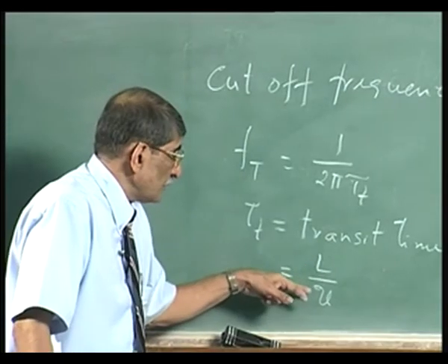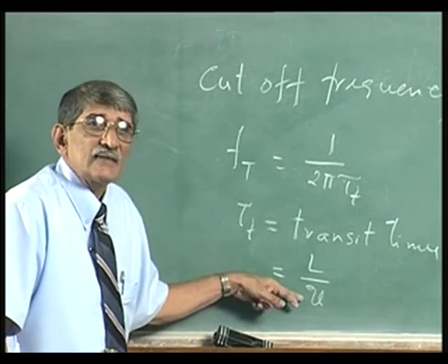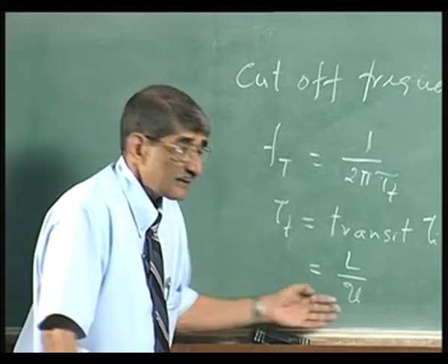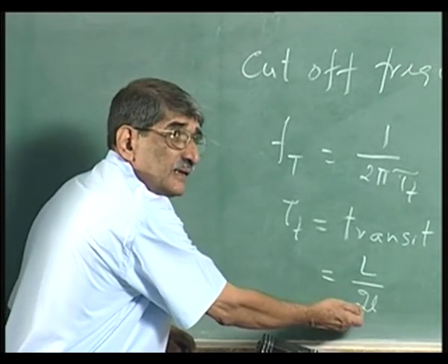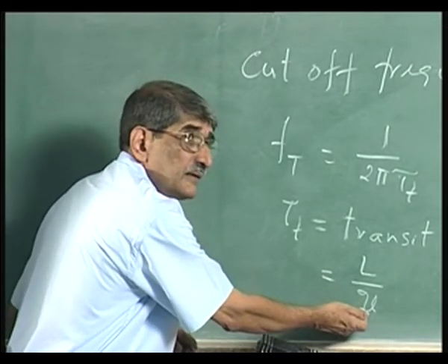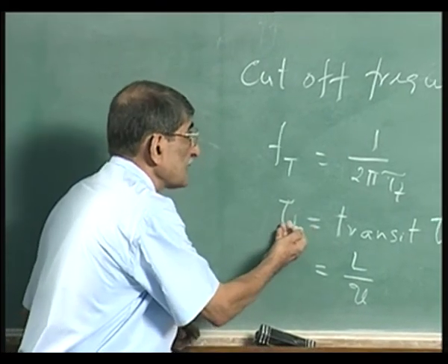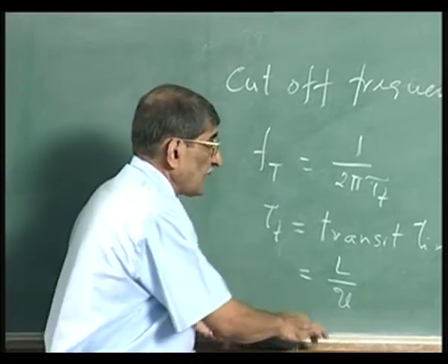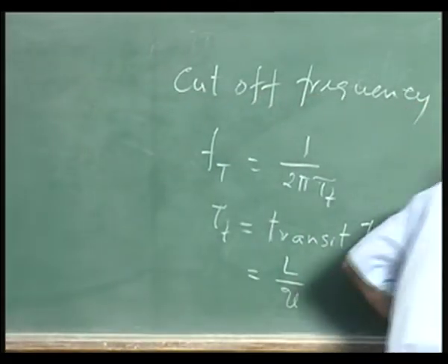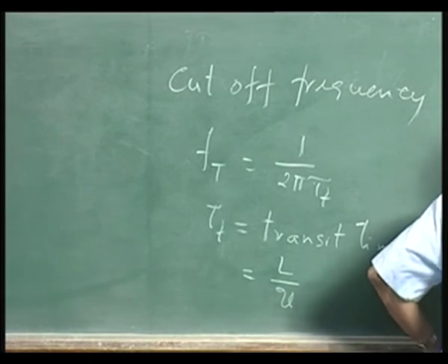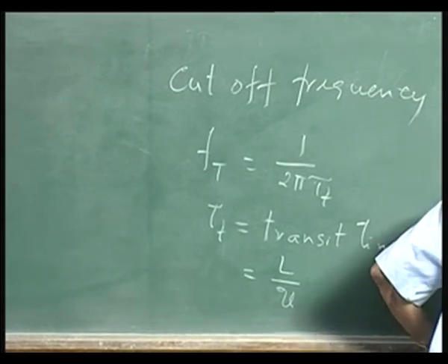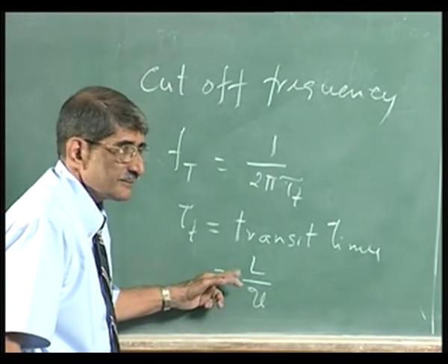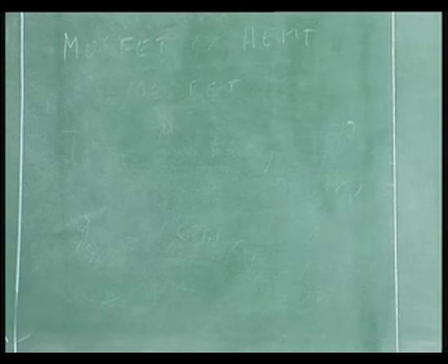Now, velocity, of course, the ultimate limit is the saturation velocity or velocity overshoot effect, all those things are there. This will be high in the case of MOSFET and HEMT, etc. It is very high. That is why you get smaller transit times, higher cutoff frequencies of gigahertz range. Bipolar, please note that you must reduce the channel length, okay, to get smaller and smaller transit times.